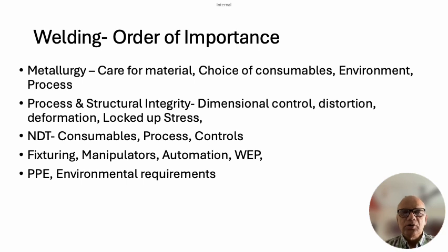So you have to think, or fixturing itself is not possible. So go back and see, or the need for fixture comes in only when by process, by proper sequencing, we are not able to control the distortion. Then only the fixturing has to really take place. And the amount of fixturing also is required to be decided properly.